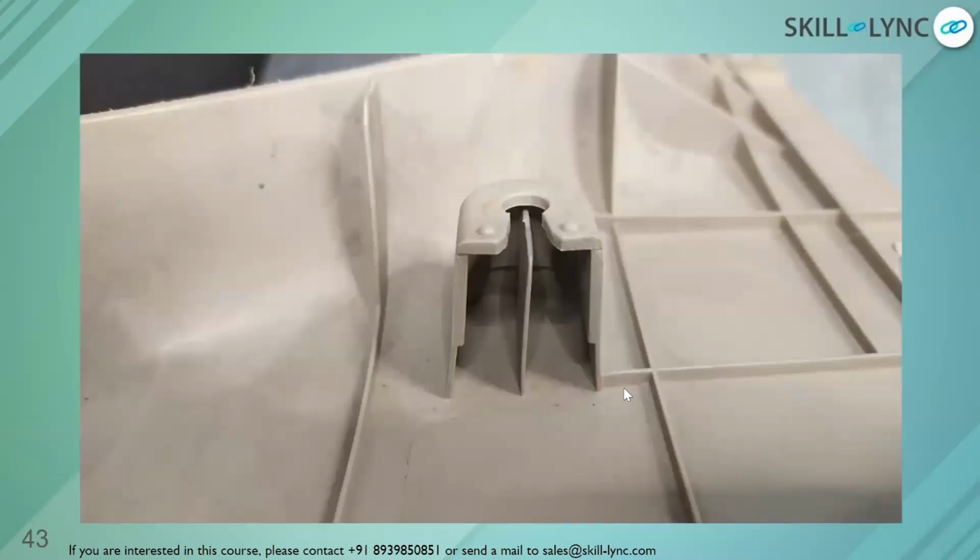So this is a doghouse which you can see in an actual plastic component. You can see how the conditions are applied for the B, the thickness at the root, the root thickness here of the doghouse. You can also see that for strength purposes it has been provided with another extra rib, as well as there is a cutting on the top. The cutting is to facilitate another engineering feature for a temporary joining operation. So we'll try to see the image with those components also.